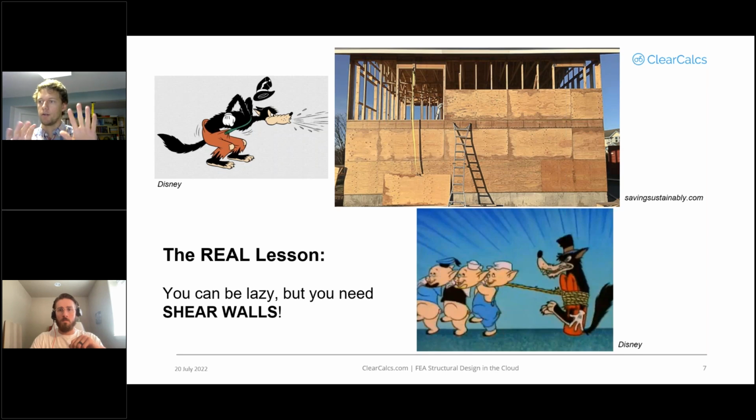So you have to think about, say, if I've got this big house, and I've got the wind pushing on a wall. That wall goes through the floor or the diaphragm and goes into the shear walls. And the floor is typically sitting on top of the walls. And that's why we'll assume that this load gets carried to the top of the shear wall.